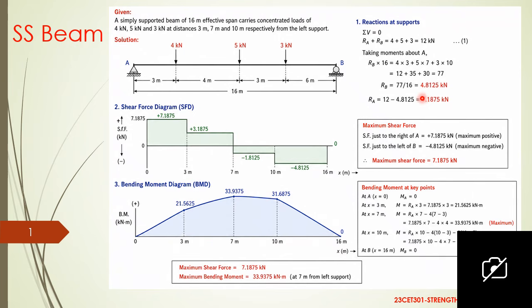7.1875 at A, 4.8125 for B. So what we have calculated is logically correct. Next, we are going to find the shear force. So shear force at A. At A, only the reaction is acting.